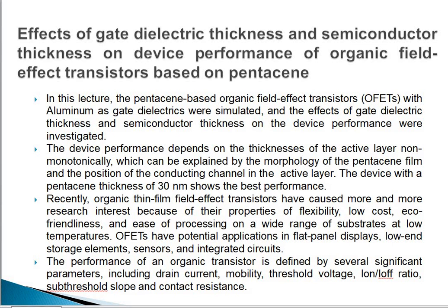The device performance depends on the thickness of the active layer non-monotonically, which can be explained by the morphology of the pentacene film and the position of the conducting channel in the active layer.